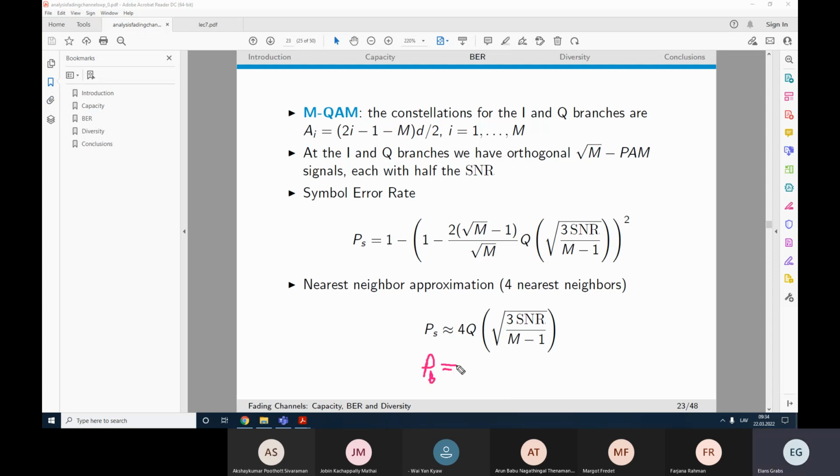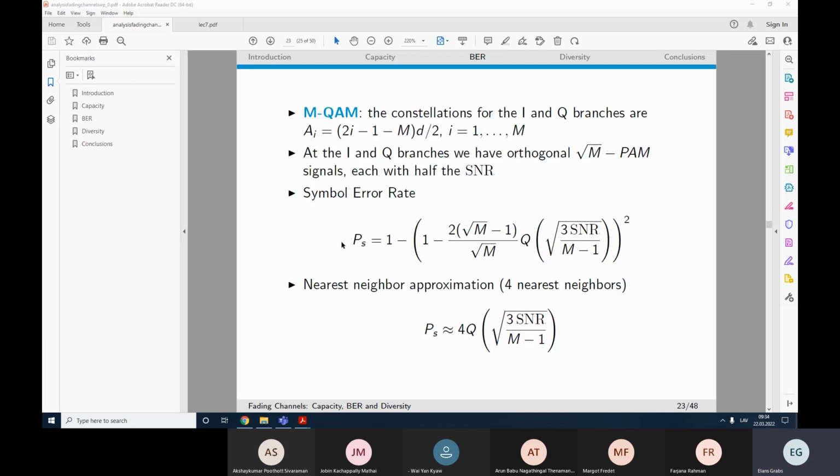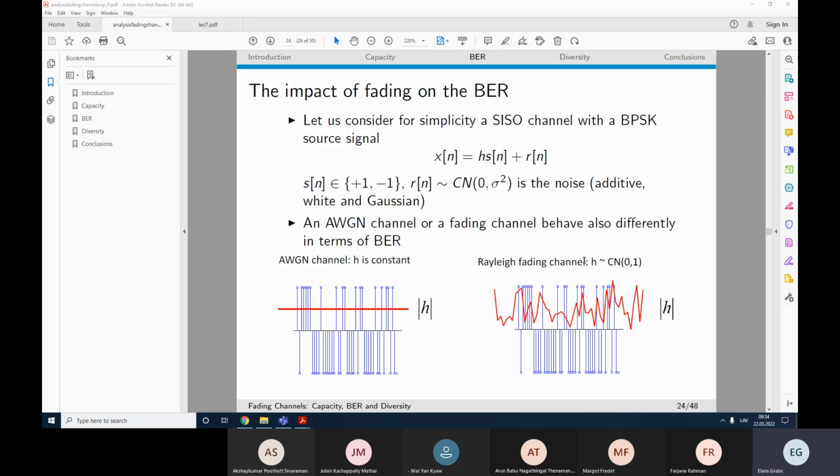It's not really like a symbol divided by 16, because there are many more different possible distances here. It's all in all much more difficult to calculate, and accordingly, most probably impossible to calculate by formula. We have to resort to some simulations, because mapping also matters. Do we use gray mapping? Natural mapping? Trellis coded modulation mapping? Yes, and well, it depends greatly.